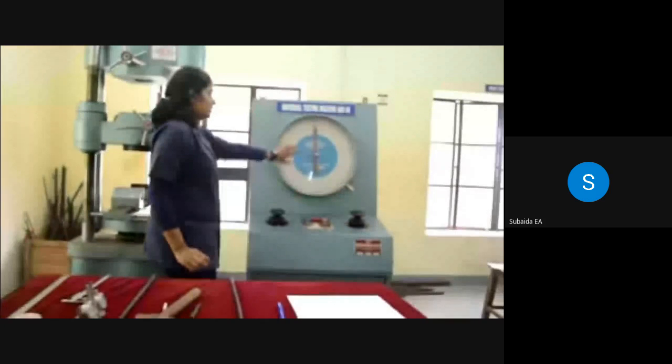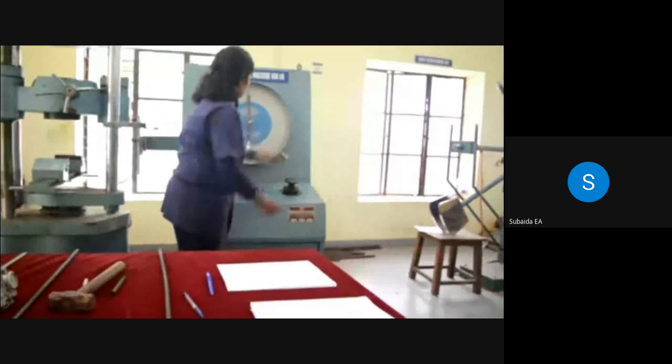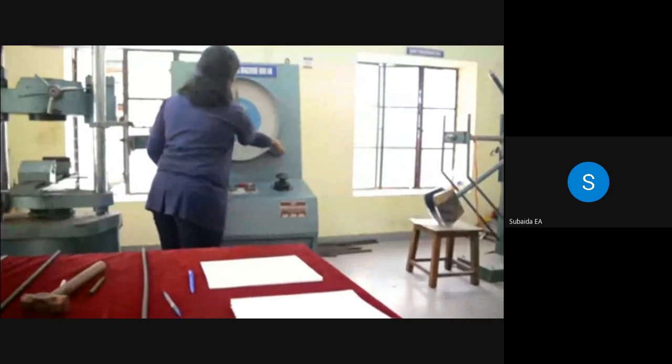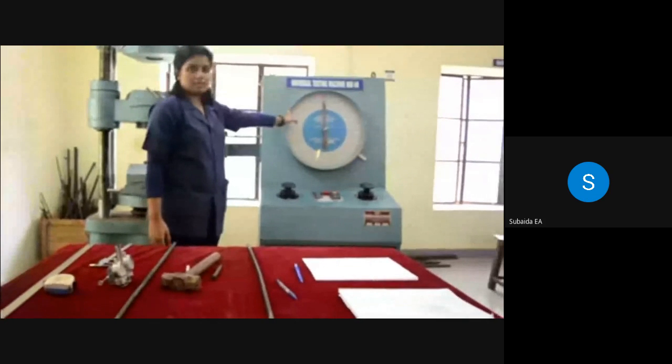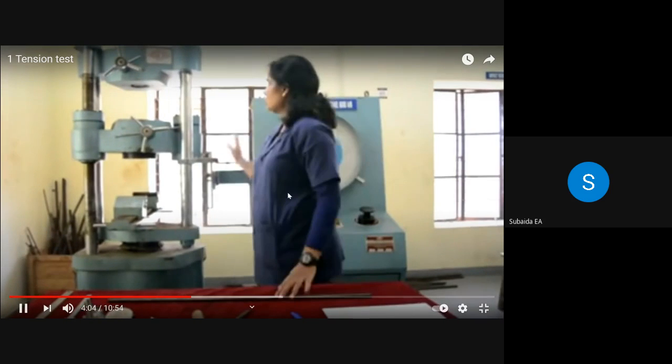So usually our expected ultimate load falls in the range 0 to 120, which can be selected using the range selector. Now behind this machine we have to put counterweights corresponding to this range. So here we are having A equal to 60 kilonewton and A plus B equal to 120 kilonewton. So for the range 0 to 120, we have to put both A and B. This is different for our machine. Our machine is a 30-ton UTM, so this load range that they are discussing may be different.